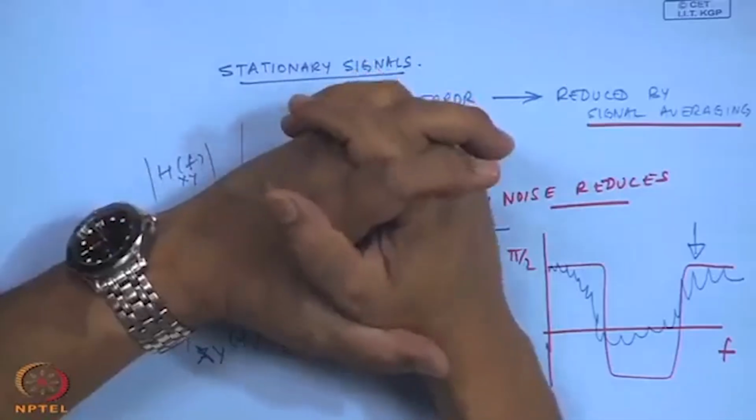So, looking at the signal in the time domain, I will see very high amplitudes, overloads occurring repeatedly, though you do what is known as auto ranging, etc. If you look at the signals in the time domain, their features may be very high, the mean and the RMS values will be high.